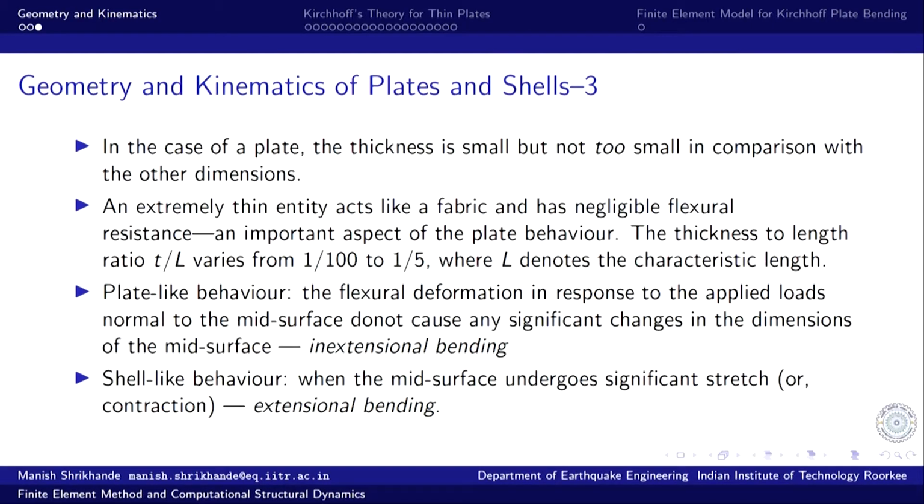A shell-like behavior is where the mid surface undergoes significant stretch or contraction, and that is called extensional bending. Quite naturally, because as we said, the predominant shell behavior is membrane action, in-plane action. The normal force is converted into axial forces, axial thrust in this membrane surface, the shell geometry or arch members.